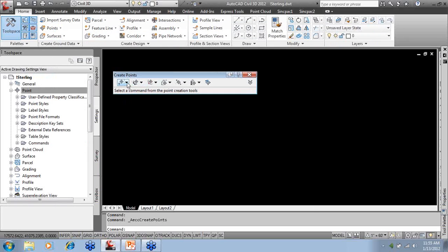Points, this is what people get frustrated on, and then they just go back to what they're using. Do not do that. This is all simple. It's just a matter of understanding it or having somebody set it up for you. So point description. Well, how about TRD? We want a deciduous tree. Let's take it a step farther. It's going to be 8 inches, and it's going to be oak. Point elevation, we're just going to say 100 real quick, and let's see what happens.